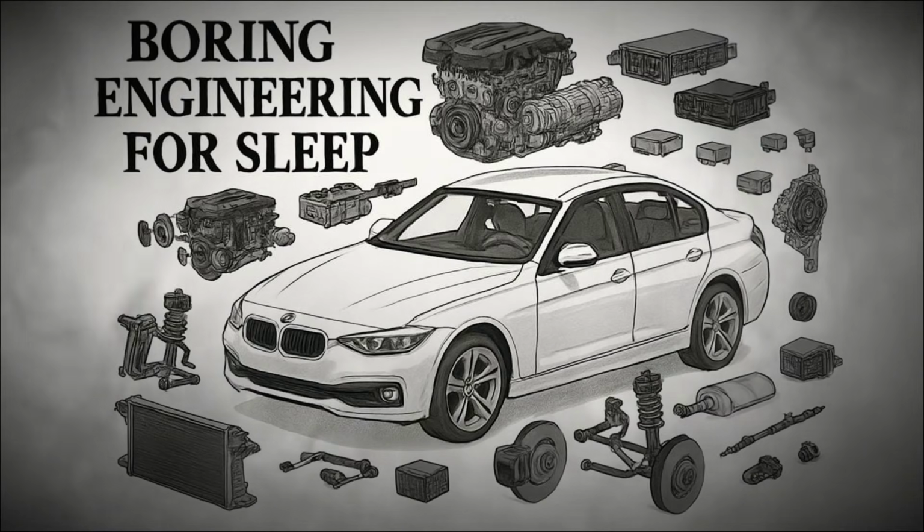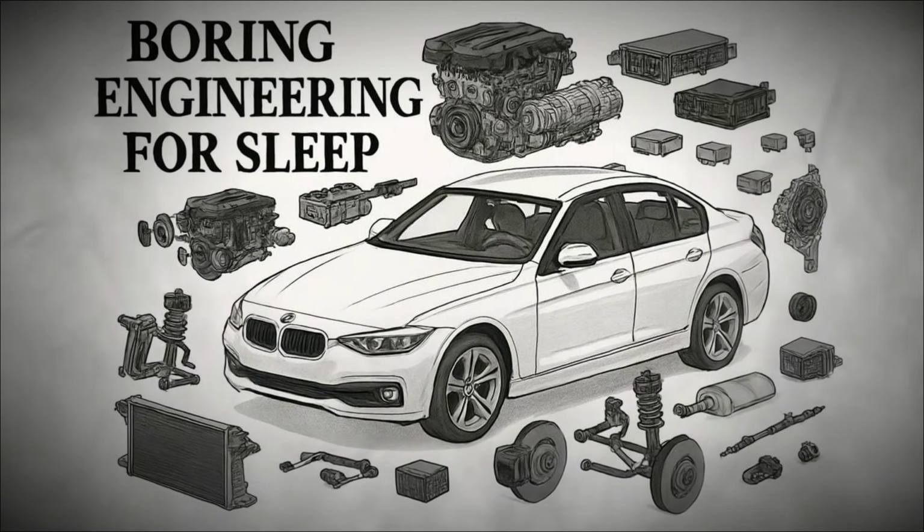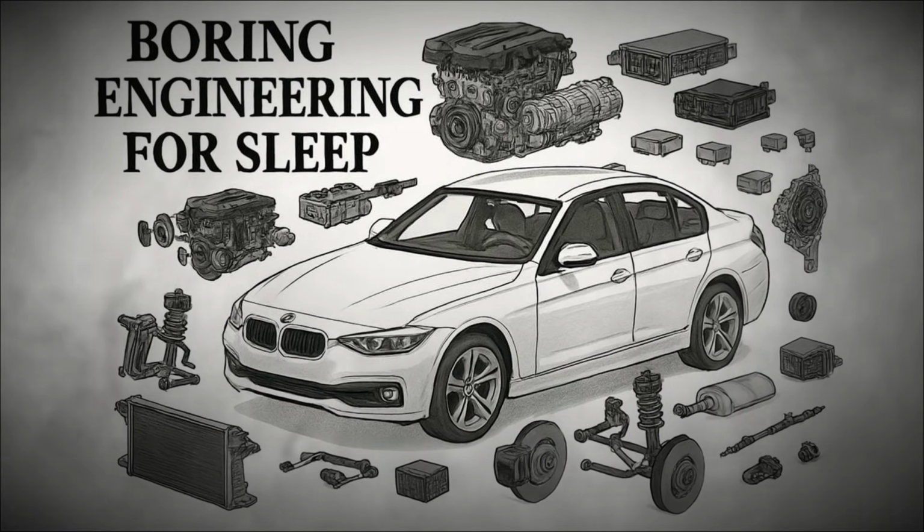One of the most significant is ABS, or anti-lock braking, which prevents the wheels from locking during hard braking. When a wheel locks, it stops rotating while the car is still moving, causing a skid and loss of steering control.